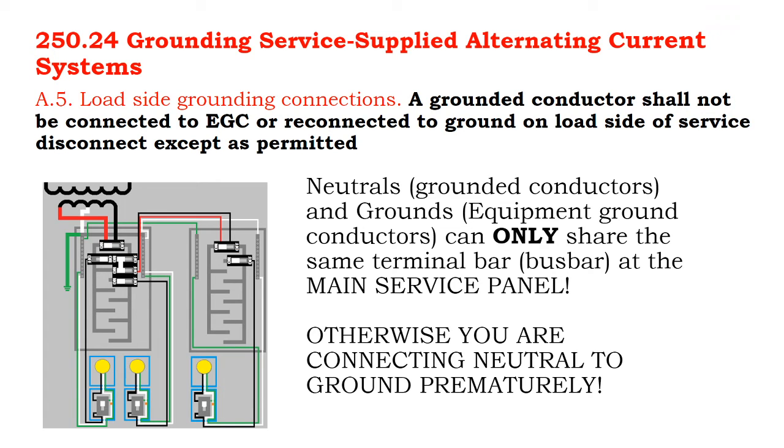Well, there's service panels where you have your neutral side and you have your ground side, and there's a metal bar that connects the two together. And then there's service panels that don't have that feature. Sometimes you have to enable that feature. Sometimes it comes shipped out of the box. Well, what's the difference?